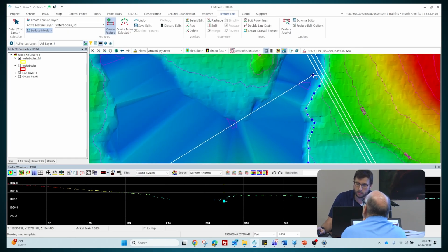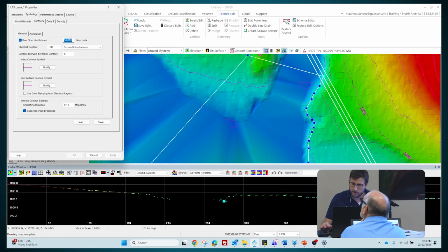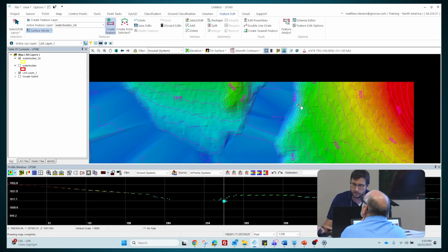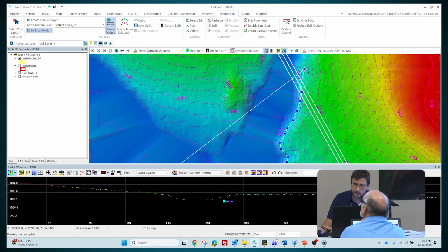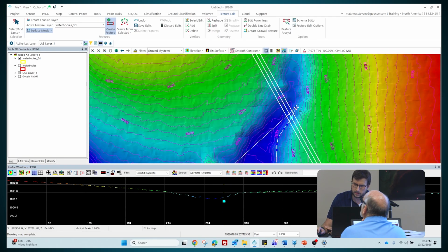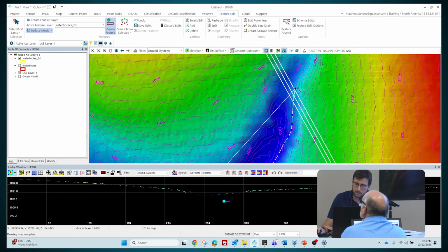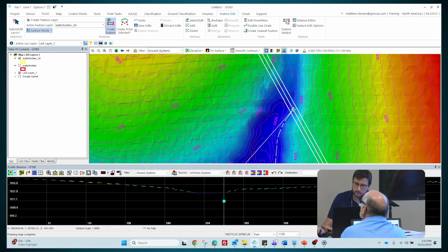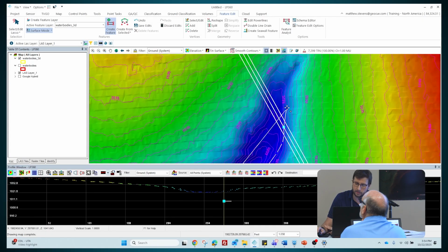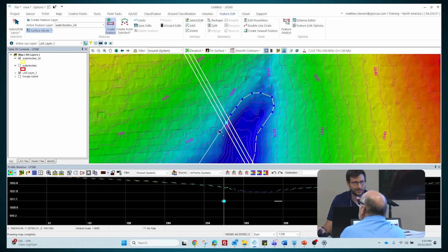And let's say you want to have even more granular contours as well. You can do a control left click on the smooth contour setting again. Let's say maybe I want 1 foot contours, so I could change to that and click OK. And now I've got a few more that I can play with for finding the edge of that water body. Let's see. All right. I'm not being super careful, and we're just demonstrating the concept here, so it's a great question.